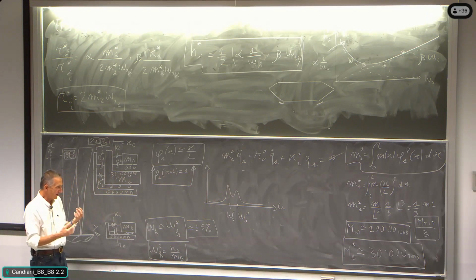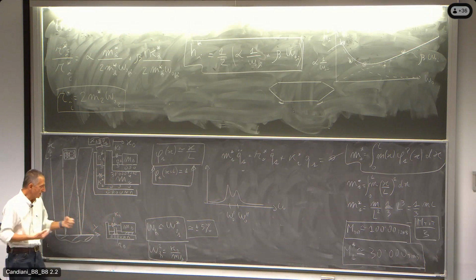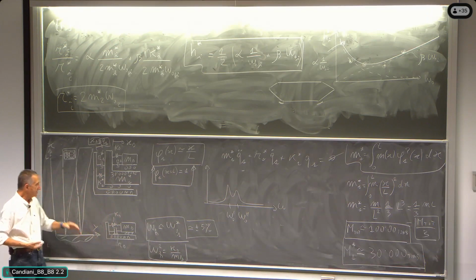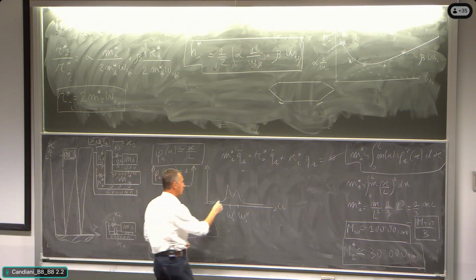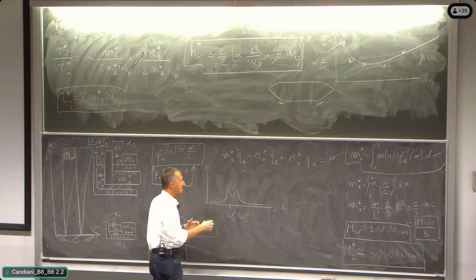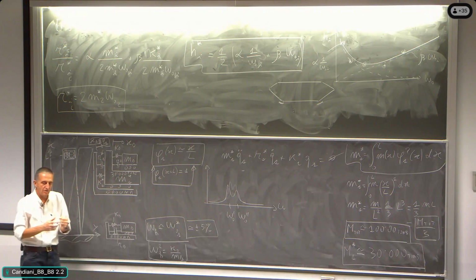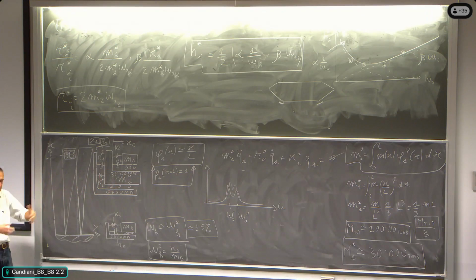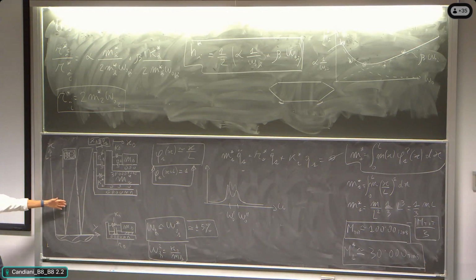Then the tuning of the system is to select the natural frequency of the damper and the natural frequency of the system that are very close to each other in order to make those two peaks a bit merging together, so that the overall behavior of this 2-degree of freedom system is looked at by the structure as an increase of the modal damping of the mode 1 of the structure.